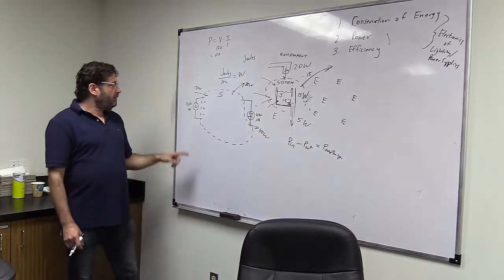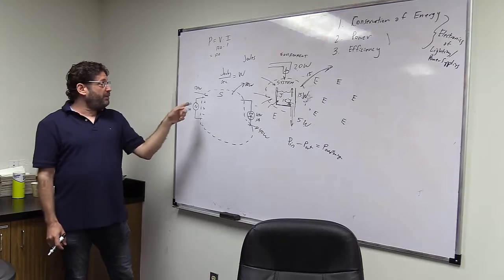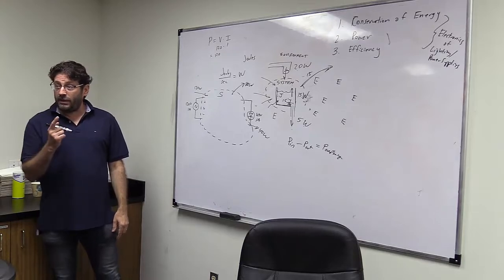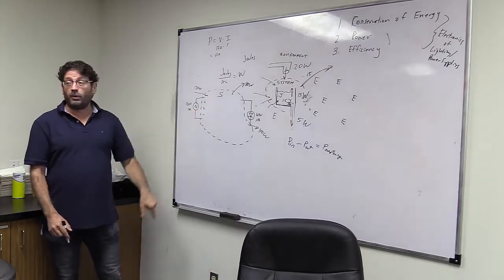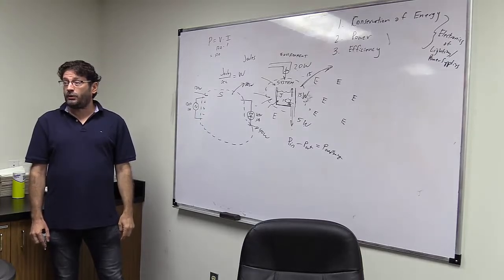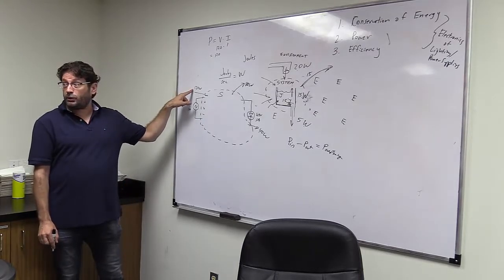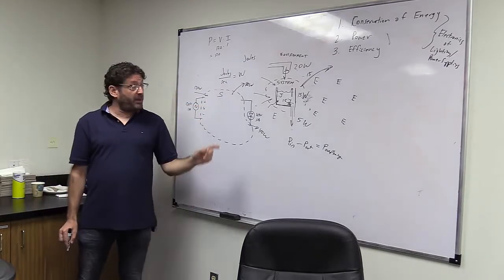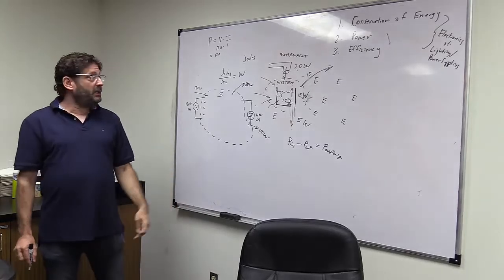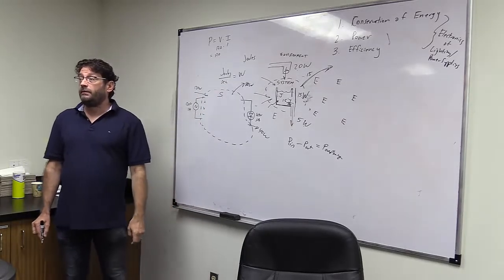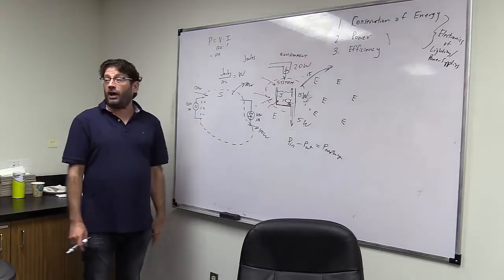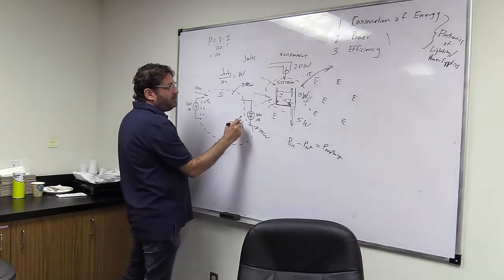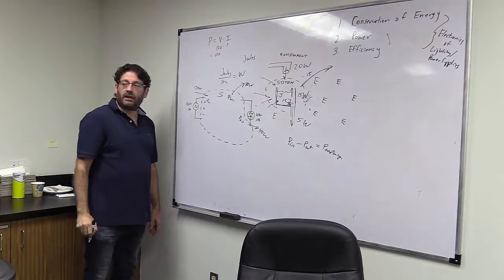Well, look at this picture. In 1 second, how many joules did I put into this system I'm using as an example? Can anyone answer that? In 1 second, how many joules are going into this example on the board? 120, because there's 120 watts, which is what? Joules per second. In 1 second, it means 120 goes in. How many is going out to my friend? 40. So another 80 is being eaten along the way, right? Somebody's dropping them or eating them along the way. They're lost. This is my power in. This is my power out. This is my power loss, okay?